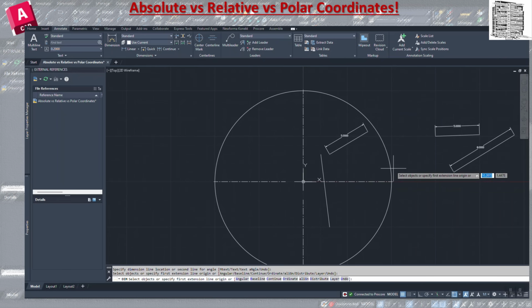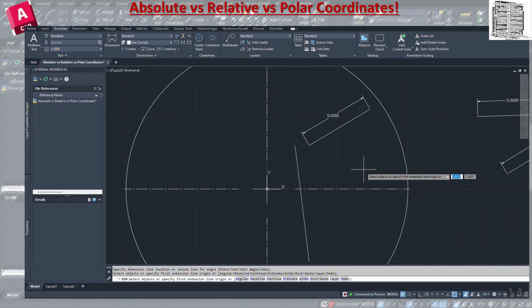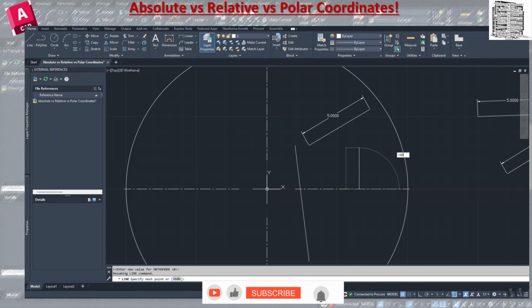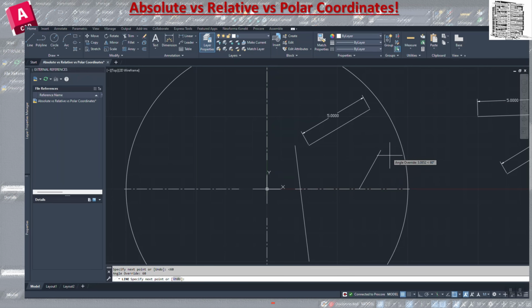Yes. So you can see, for drawing an angle with a certain length that you want, you just need to click on the line, click anywhere you want, and then follow up with the angle sign. Let's say 60 degrees, enter, it's going to lock it at 60 degrees, and you can see it on the screen. Right now you can put your length, 4, and put the 4 over there. So this is showing you how to insert angles anywhere you want, and if you want to restrict a certain line to a certain angle, this is a way to do it.